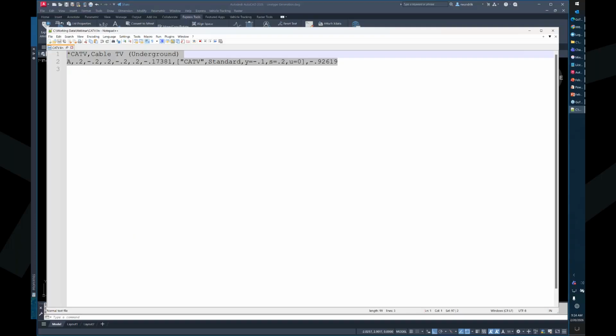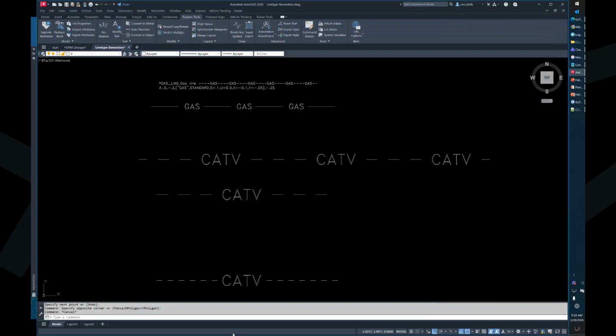And note, not the line type scale, the annotation scale. Because anytime you're working with an annotation scale that's not 1-to-1, down here, the results you get may not be exactly what you expect. The line type scale should just be 1. Or in the case of architects, it's 0.5 because AutoCAD Architecture and AutoCAD MEP automatically reset line type scale to 0.5 for whatever reason.